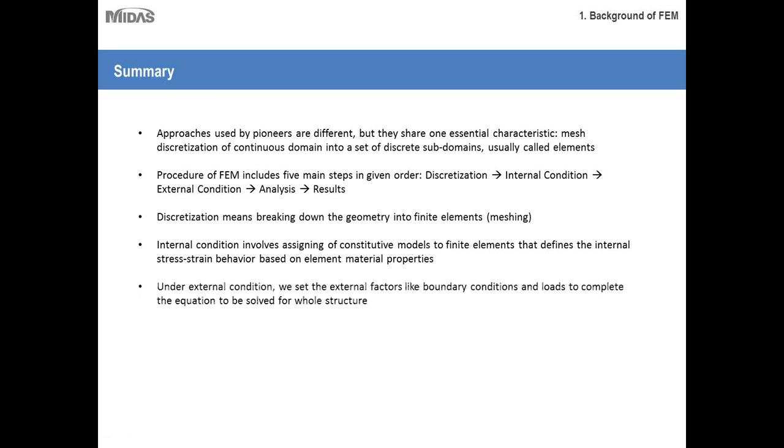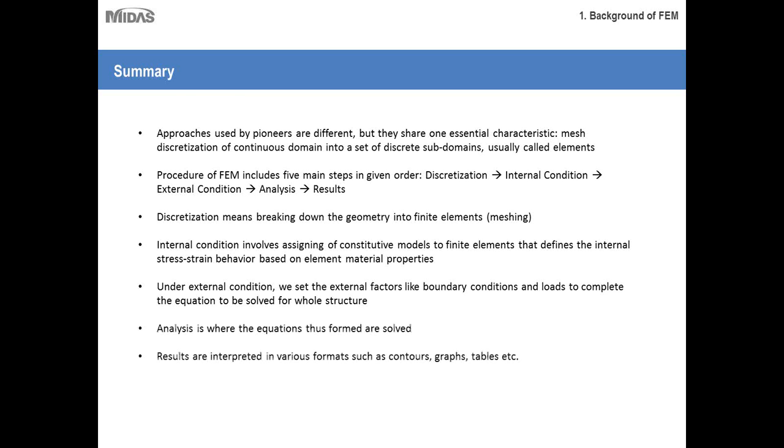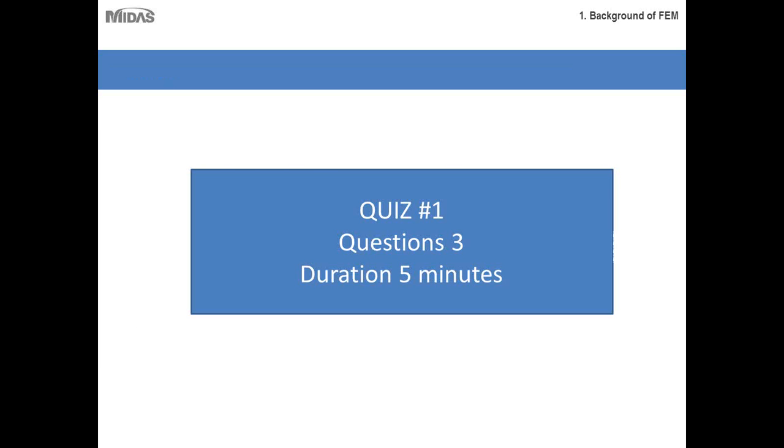Then under external condition, we set the external factors like boundary conditions and loads, to complete the equation to be solved for the whole structure. And analysis is where the equations thus formed are solved. Then results are interpreted in various formats such as contours, graphs, tables, etc.